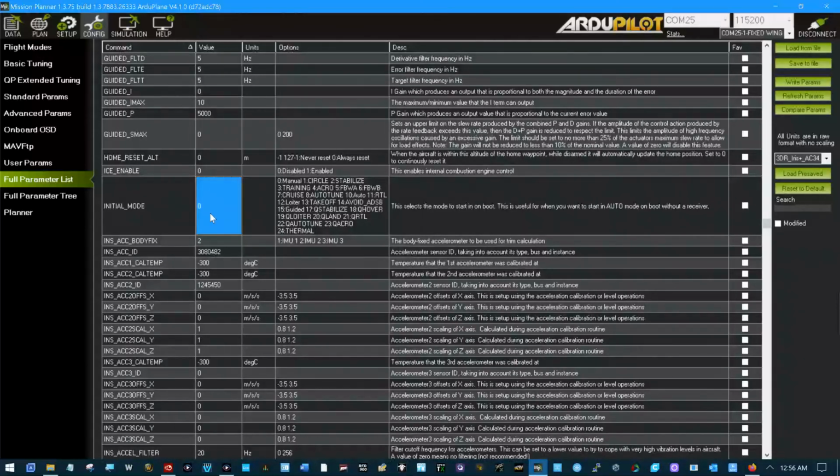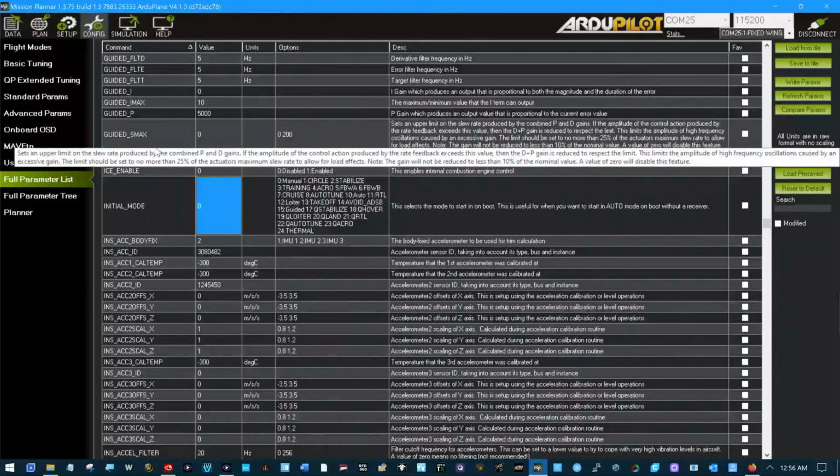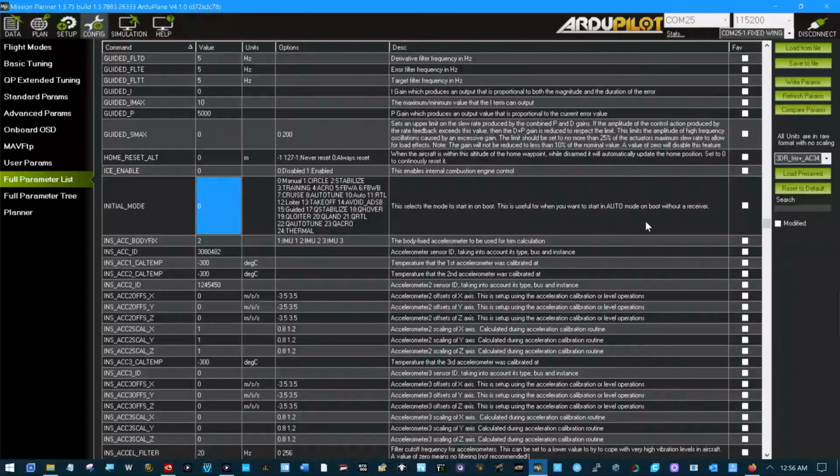The input signal's modified slightly based on the orientation of the platform. If you're in a guided mode where you've told it that you can't bank more than 45 degrees, it's not going to let you bank the plane any more than 45 degrees. Your input signal's being modified by the flight controller. In manual mode, nothing is being modified.